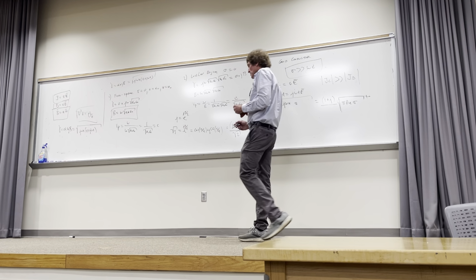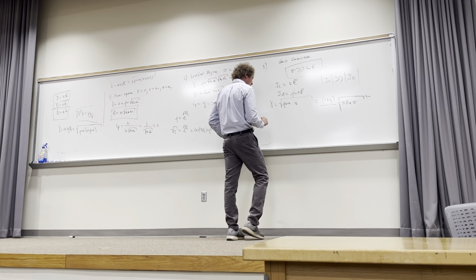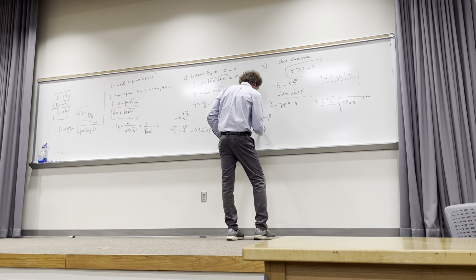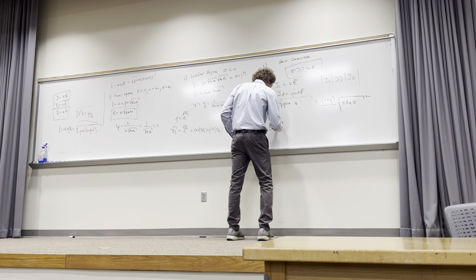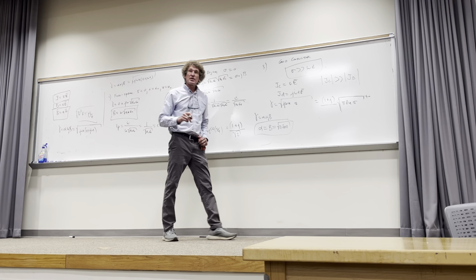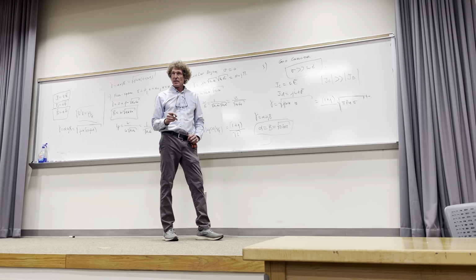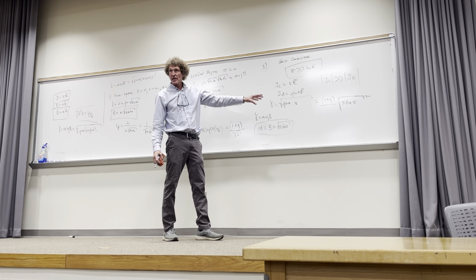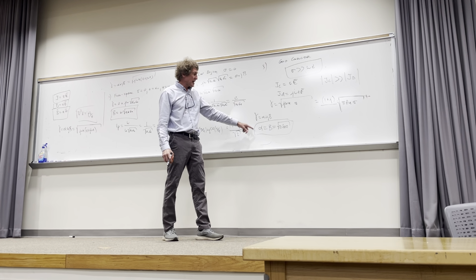And here's the kicker that you write down. Make sure you write this down. You can say gamma is equal to alpha plus j beta, and alpha in magnitude is equal to beta is equal to the square root of pi f mu sigma. Y'all with me? This is for a good conductor. Now the reason I did it that way, I mean, y'all see this right here? I'm doing it to show you the trick. Once you get down to that point, I have beta, right?